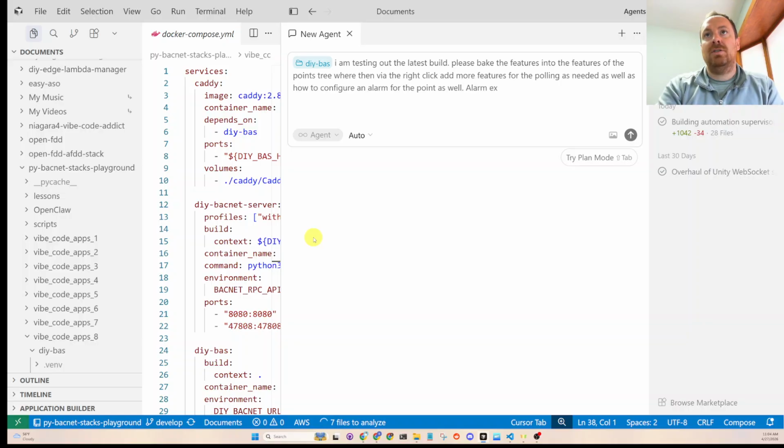Alarm extensions typically need a high and low value for numeric type of point, and then for a Boolean type of point for a fan status or pump mismatch.